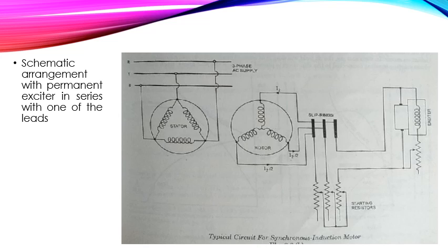After a short delay, the exciter voltage builds up and field current is caused to flow through one phase of the rotor winding to the star point, where it divides between the other two phases in parallel, each of which carries half the exciter current, and the rotor MMF is almost sinusoidally distributed. As this field is established, the machine pulls into step and operates as a synchronous motor.